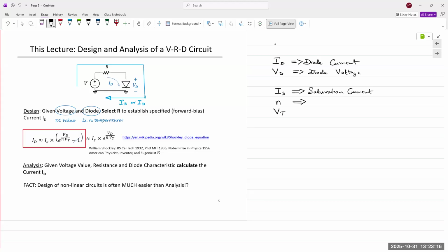Semiconductor devices are made up from two different kinds of semiconductors. There is a P-type material and an N-type material. When you bring a P and N-type material together, we get what is known as a PN junction. P-type material has an excess of holes as semiconductor carriers, and N-type material has an excess of electrons as semiconductor carriers. When electrons flow, they're carrying the charge with them. Holes are the exact opposite of electrons. It's the absence of an electron that creates an empty spot inside a semiconductor material, so it's a hole, and it's positively charged. Electrons move one way, holes move the other way. And so in an N-type material, there is an excess of electrons.